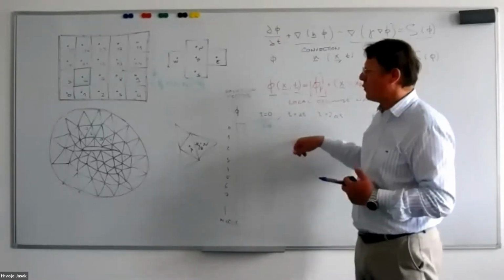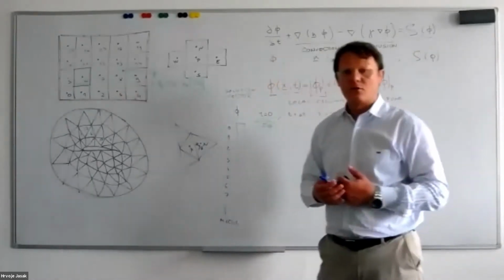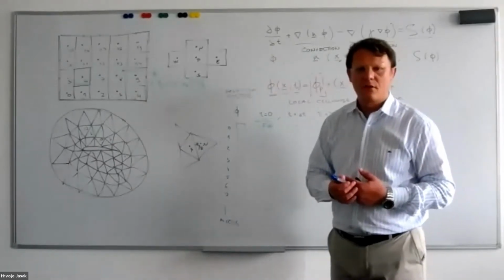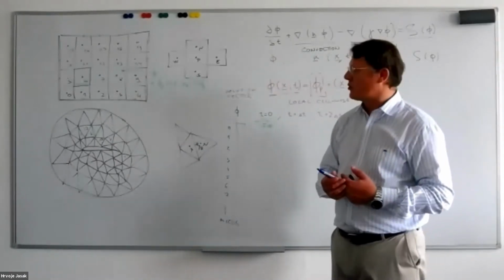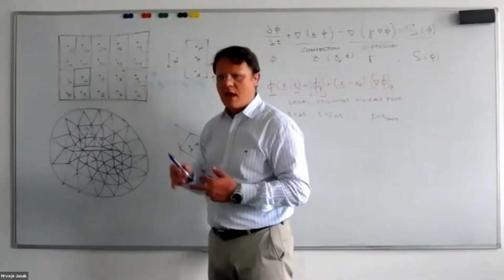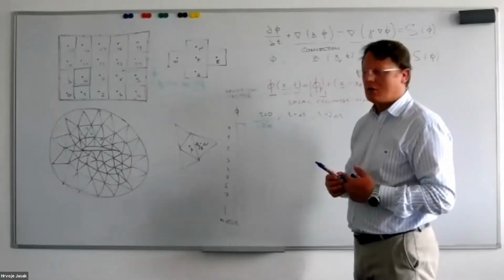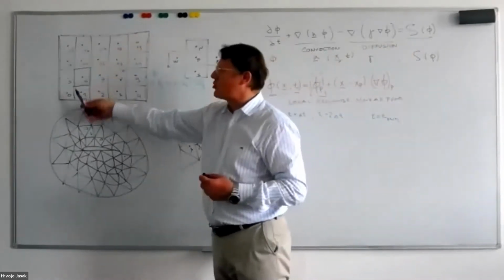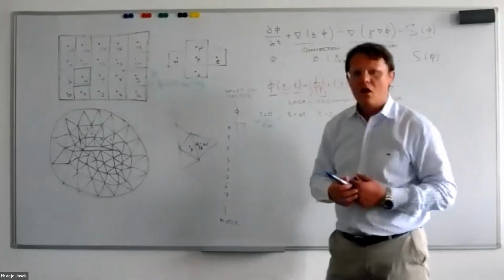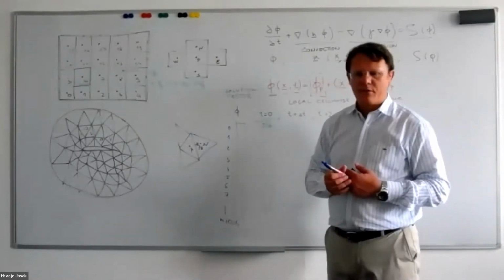The information will be the geometric information, cell volumes, face areas, etc. Connectivity information, saying which cell is connected to which neighbors. And finally, boundary condition information, which describes the interaction of my computational domain with the rest of the universe. How will I perform that?